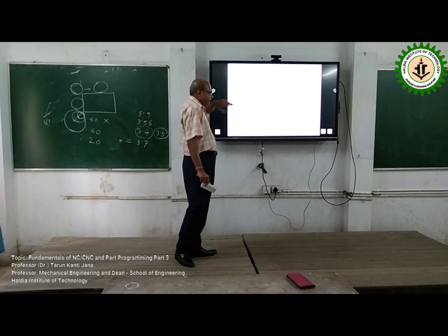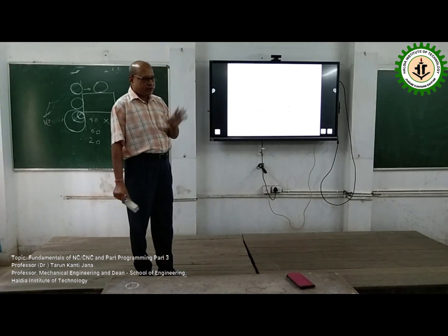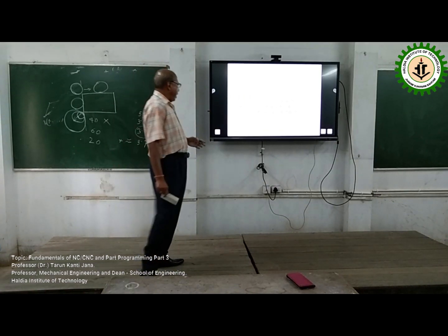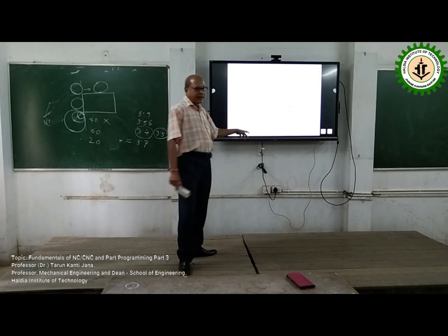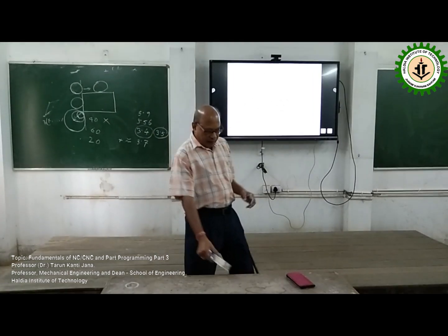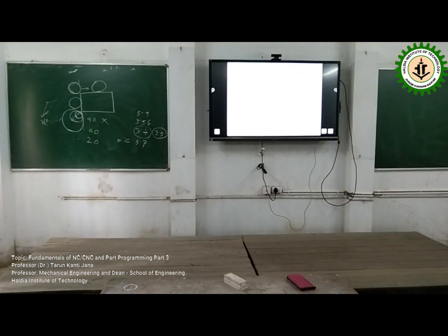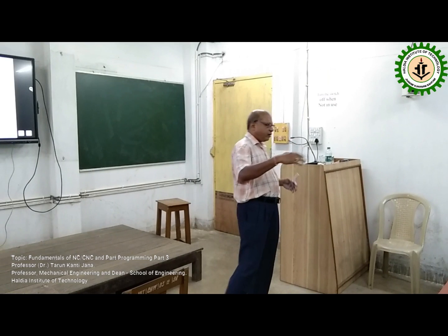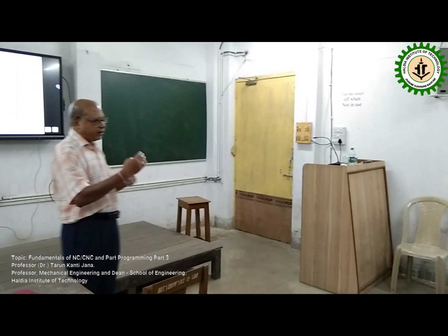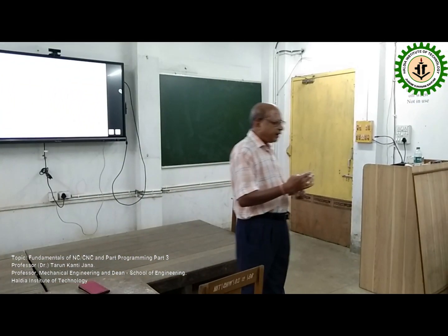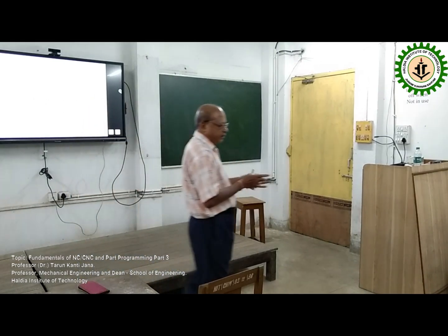This is also another feature, as such not that much pertaining to the milling machine, but related to the turning center or lathe category. And these are some of what we call dedicated cycles or canned cycles. If you write a manual program repeatedly, then it is very boring. The number of lines or blocks will be enormously high, and it will take a lot of memory space. So in that case, there are a lot of dedicated cycles, popularly known as canned cycles or fixed cycles, which are developed separately, dedicated for specific types of operation.